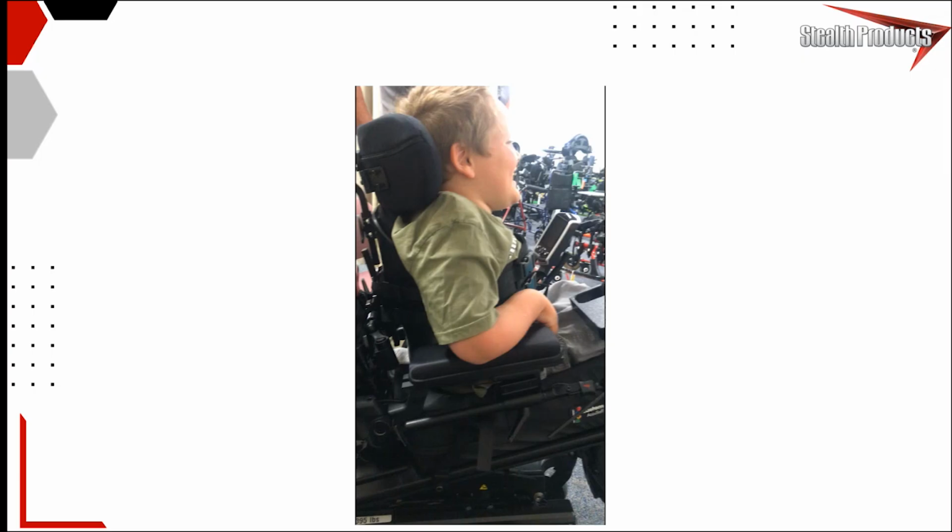To drive. So the tray also has hardware that allows for height adjustment of the joystick, so you can have it come through at the right position for him. And in his case, that tray should have a track that would normally allow for side to side adjustment, but in his case, it would be front to back adjustment of the joystick. So again, you can really finitely place that thing where he needs it.